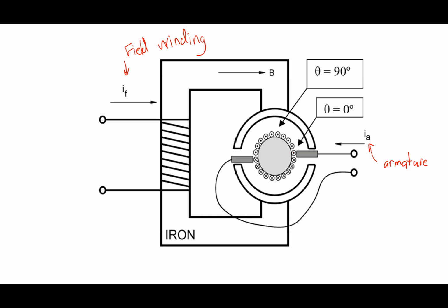So that's the basic picture of what it looks like. If you want to see it some more, you can come up. I'm happy to let you take a look at it. But basically, those are the pieces that I just showed, shown together, right? These pieces here, there are these two copper strips, and attached to those copper strips, you can see something a little bit bulky on the ends. That's made of a carbon material, graphite type of material, and it's called a brush, right? This is what I call a brushed DC motor, because it's like I have a brush touching this thing as it rotates, right?